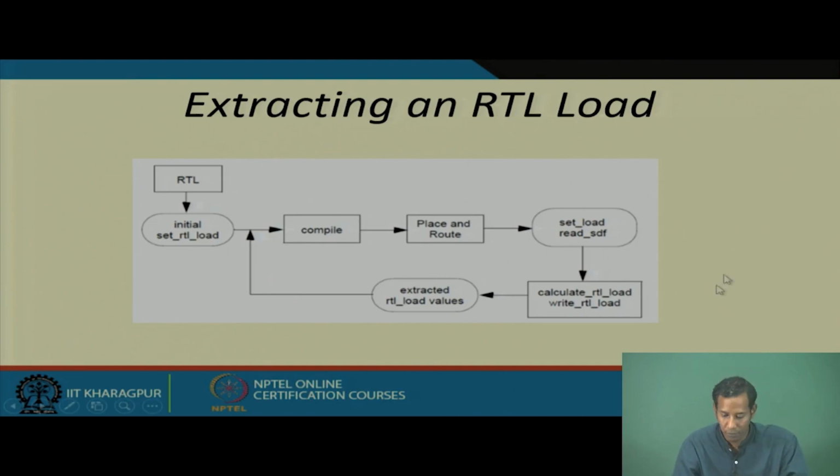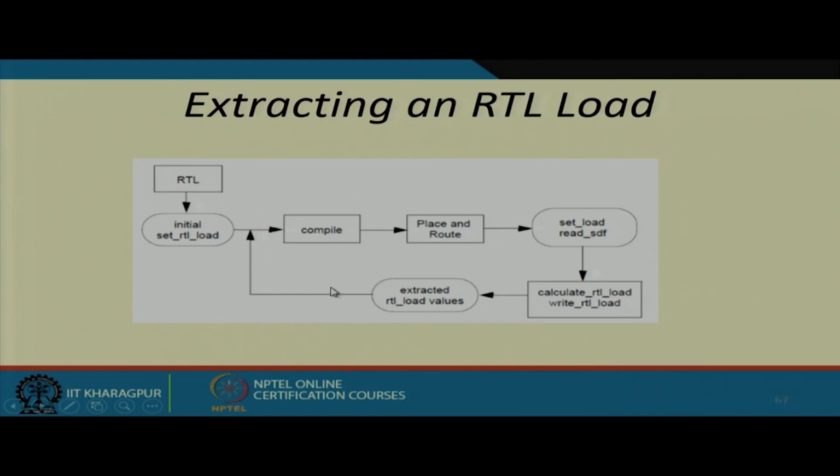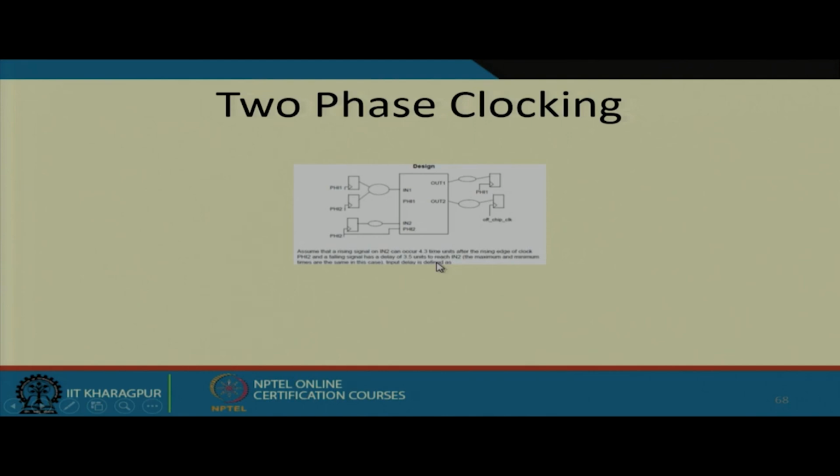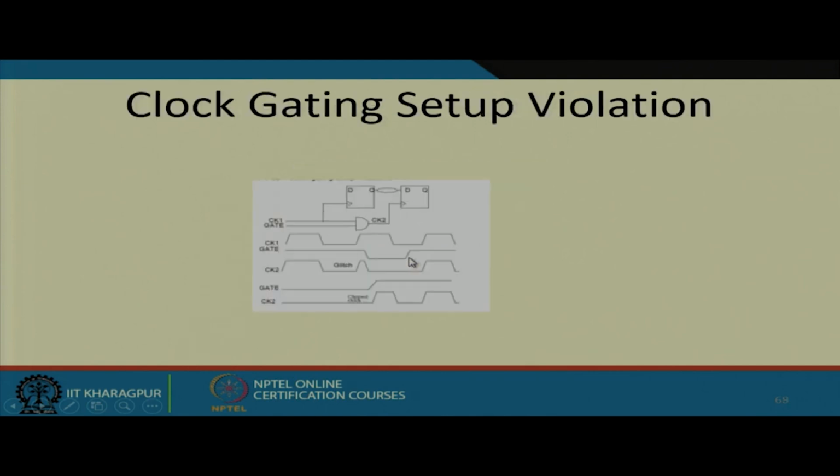Now, the actual time will be calculated based on this particular loop. If the actual time is more than 5, at that time you will get negative slack. If this path corresponds to a lesser value than the required time, you will get positive slack. Okay.